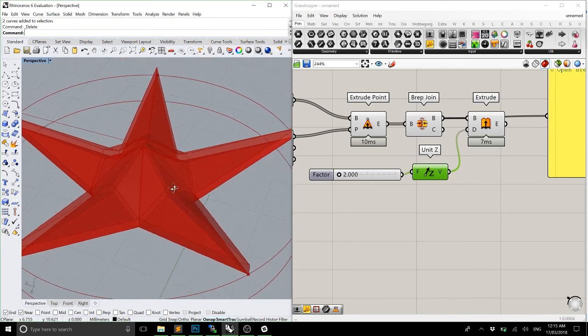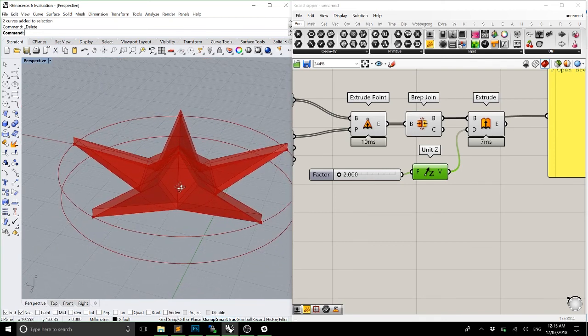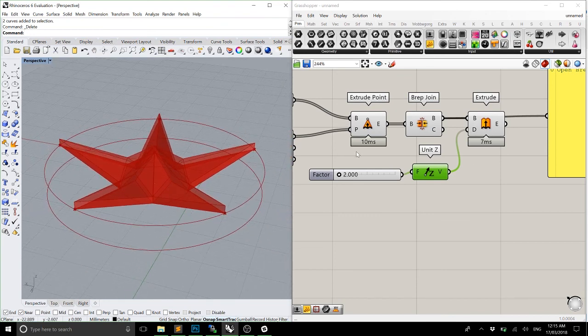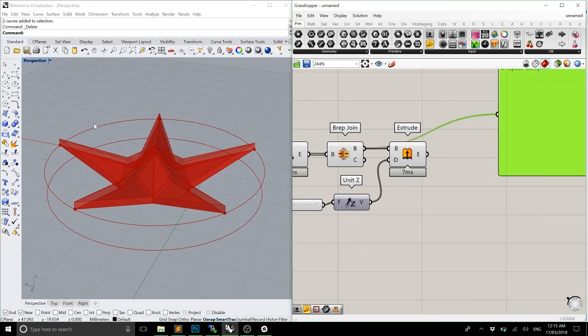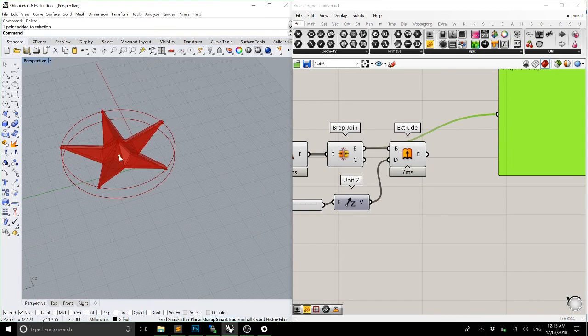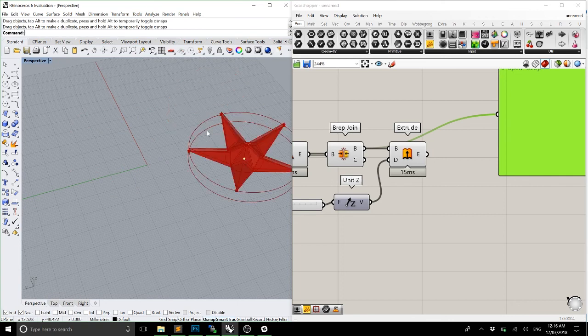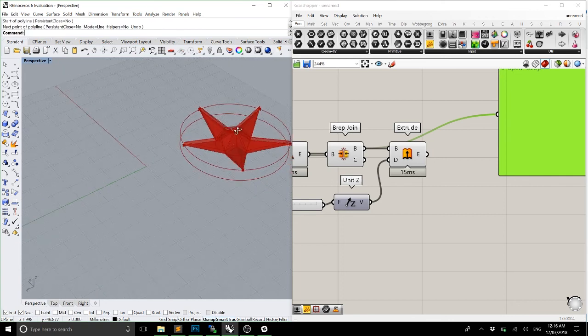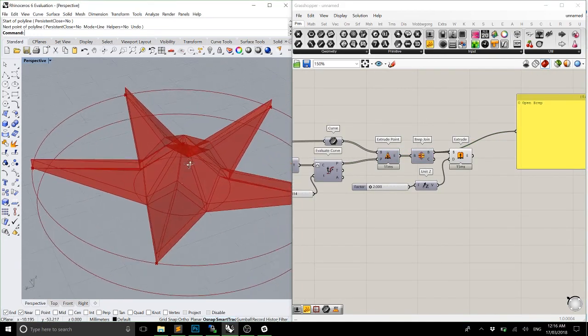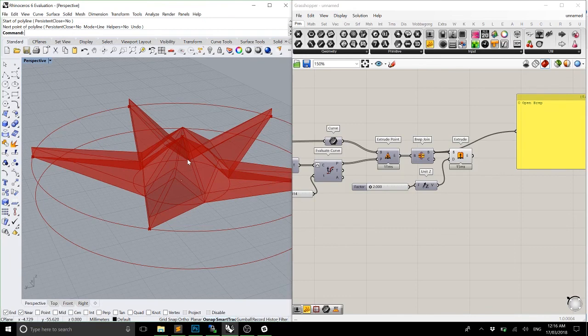And we're on the home stretch now, because there's only one button. We're 1 button away from getting this back into Rhino. So at the moment, we're looking at dynamic geometry right now. I can select the point in Rhino, I can move it, but I can't select the extruded solid that we've just made. So we need to get this back into Rhino so that we can then export it for the 3D printer. And to do that, we need to bake.